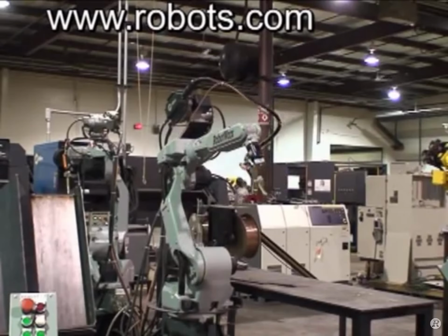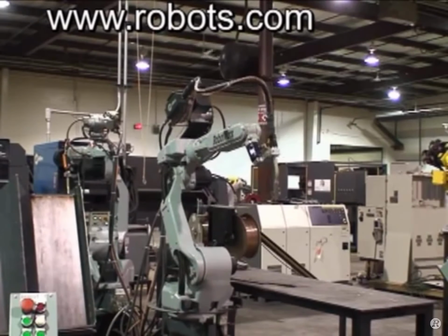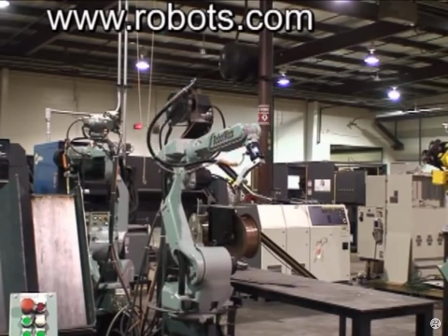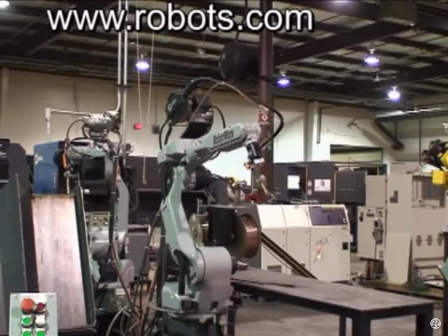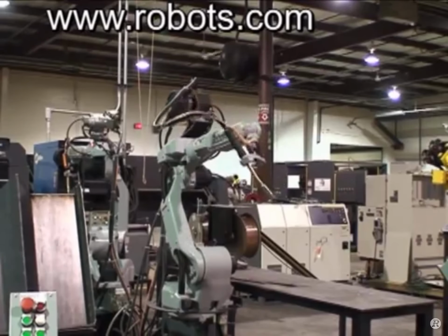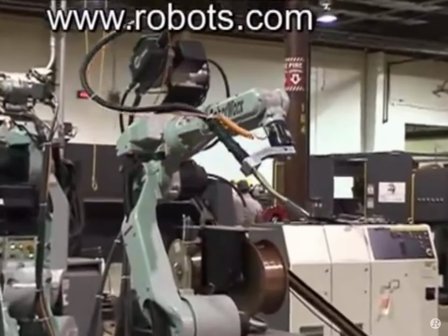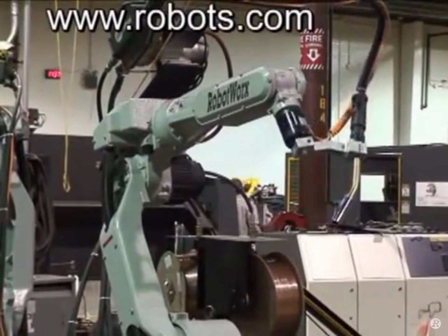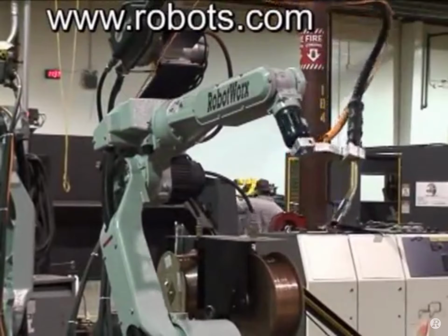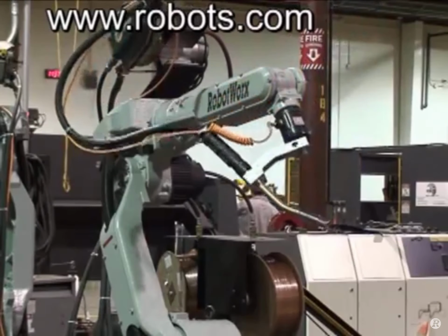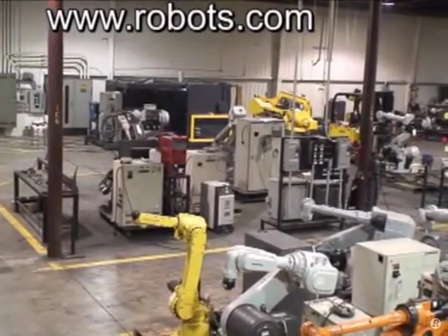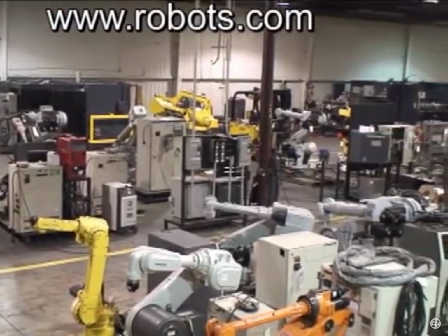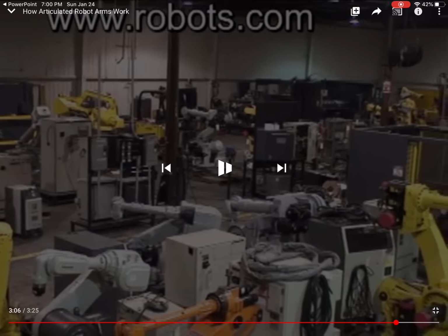Axis 6. This is the wrist of the robot arm. It is responsible for a twisting motion, allowing it to rotate freely in a circular motion, both to position end effectors and to manipulate parts. It is usually capable of more than a 360-degree rotation in either a clockwise or counterclockwise direction. The most popular 6-axis robots are manufactured by Motoman, Fanuc,